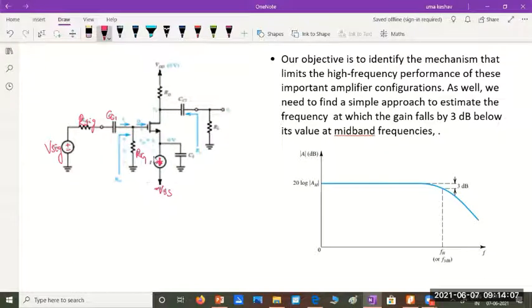And we know that any element in the source causes negative feedback, just like the source resistance. So there will be a source resistance here to have a constant current source, giving a complete circuit of amplifier, MOSFET and current source. So I have to bypass it with a bypass capacitance. You can see here this CS is a large capacitance which is normally called the bypass capacitance. CC1 and CC2 connected on the input and output side are the coupling capacitors.